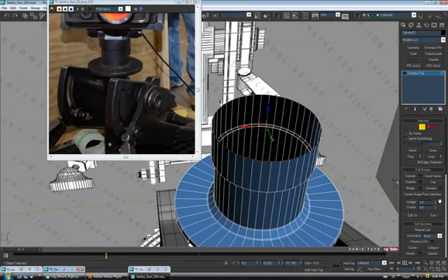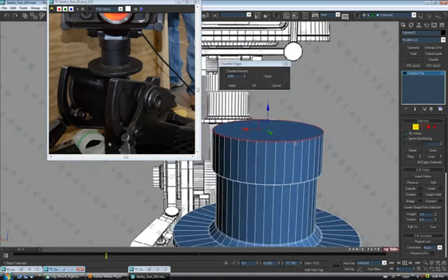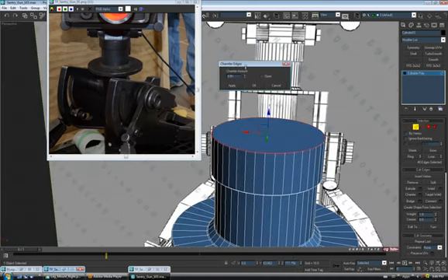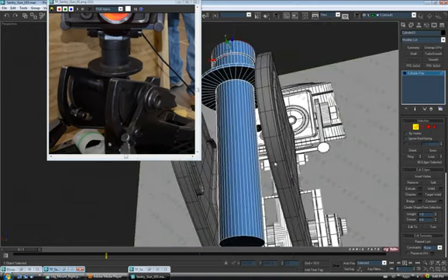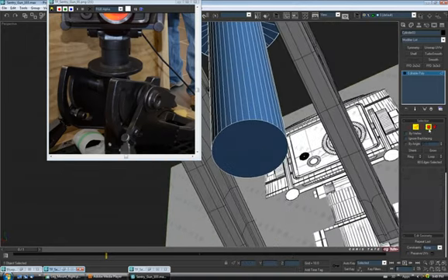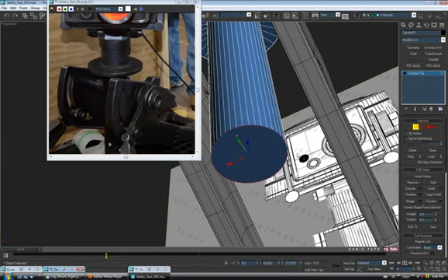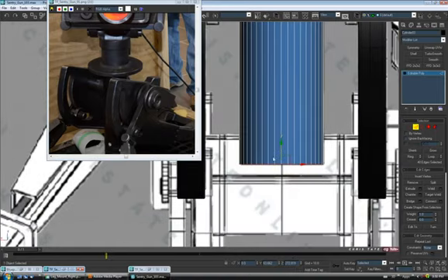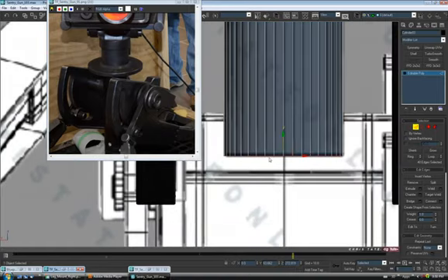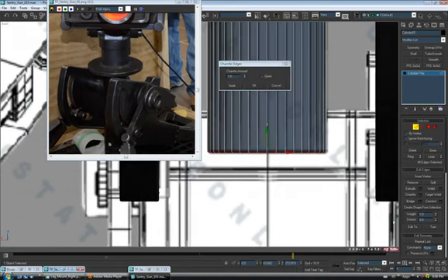So I'm going to go to border, grab the top, we'll hit cap. I'm going to control click edge, and we'll just chamfer this down. For this one, I might just widen it out a bit. Alright, we'll do a 1 on that. Okay, and let's go down to the bottom here. I'm going to grab that bottom face and control click edge just to get the edge selection, and then let's maybe do this in the front view. Alright, so we'll zoom in down here, and let's chamfer it. Let's do maybe 1 on the first one.